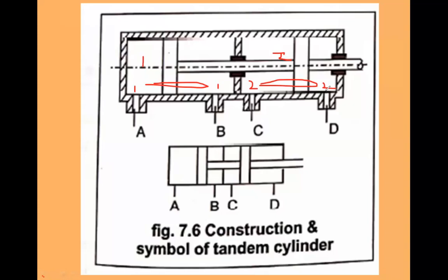That means greater force can be obtained by this tandeming, at the same pressure, without increasing the piston size.